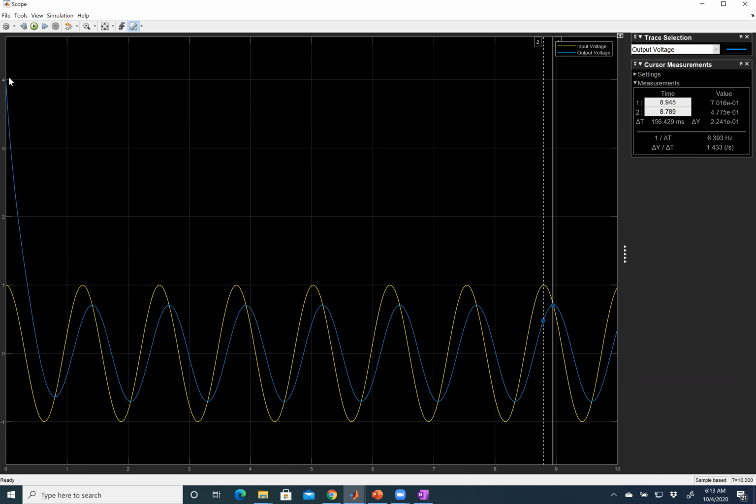And we see that it starts at 4, just as we said it would, because we gave it the right initial condition. Here we see the transient response. We said it should be done in about a second or so, 5 time constants. Looks like it is. By about a second, our transient response is more or less dead, and we're left in steady state, as we'll be for a long time if we leave this turned on forever.